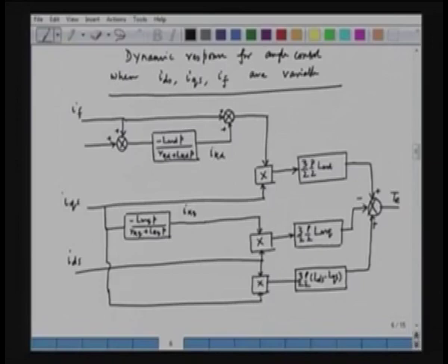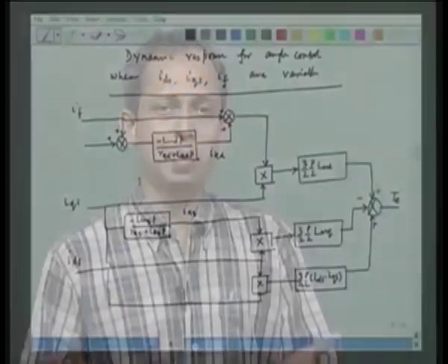Now, we have already seen how complicated the equation for the torque is. Here, this is a general situation where everything is variable, gamma is not equal to 0, which is angle control, and all possible torques are present here: the field torque, the damper winding torque, and the reluctance torque. So, this is a very general situation.